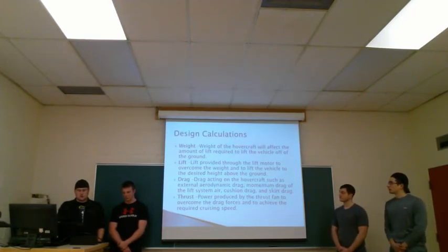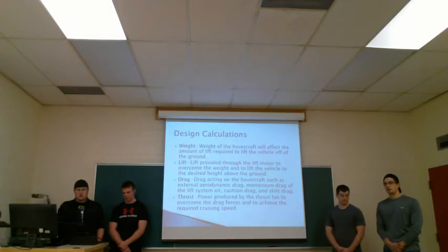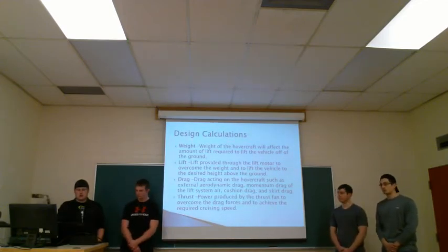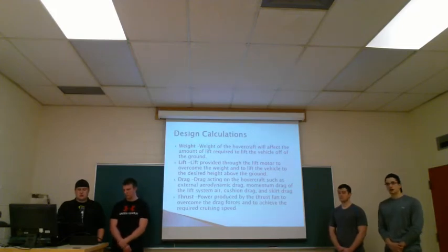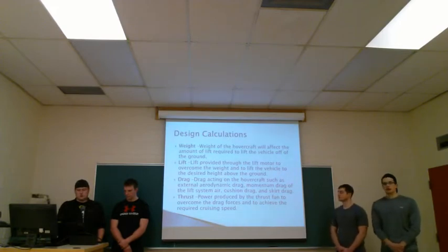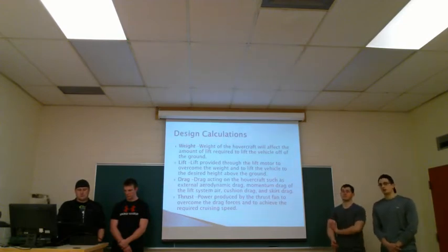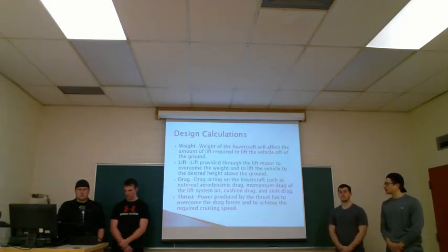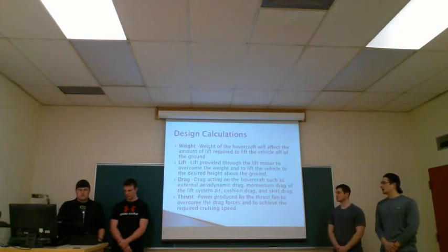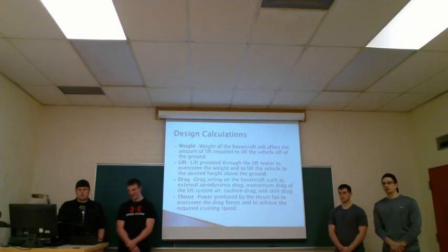Then from there, the lift provided will be based on the size of the motor and propellers that we purchase, and the drag force acting on the hovercraft, such as external aerodynamic drag, momentum drag of the lift system, cushion drag, and skirt drag. This will also help us determine the propulsion motors on the back. And the last one is thrust, the power produced by the thrust fan to overcome the drag force.